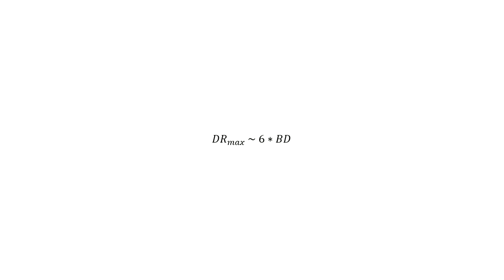What happens when you work at 24 bits but then decide to export your file at 16 bits? We are losing information, are we not? And that is bad because losing information means losing the possibility to reconstruct the original sound without artifacts and distortions, right? Yes, but there's a way around the problem. A technique called dithering uses the fact that our ears are very good at picking out individual frequencies from a sound, but bad at picking out random noise at many frequencies. Dithering mixes in random noise into the original sound to fake our ears into thinking every bit of information is there. This process is also used when moving up the bit depth ladder instead of down.